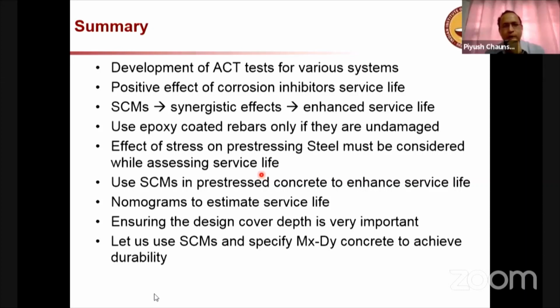Final question. Protective coating in reinforcement reduces bond between concrete and steel. How can we rectify this problem? And which corrosion protection method is cost effective? See, I would say go with very good concrete. That's the best thing, because otherwise it's cathodic protection, but there are also issues associated with applying cathodic protection on coated steel.